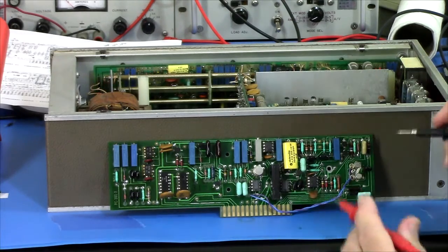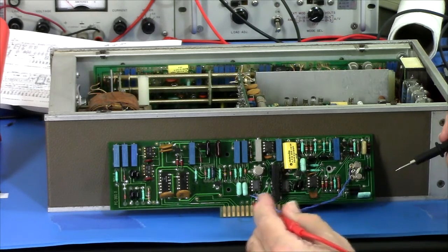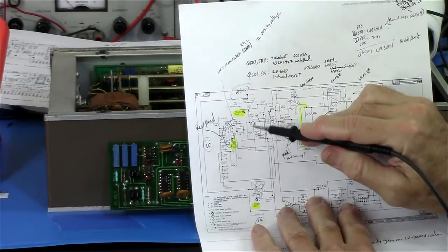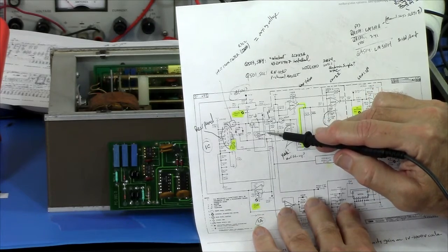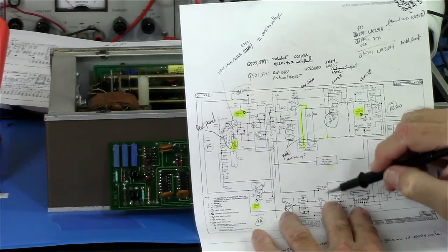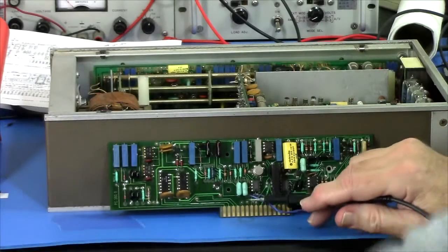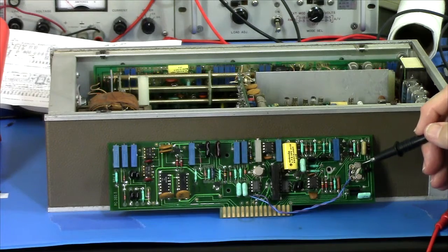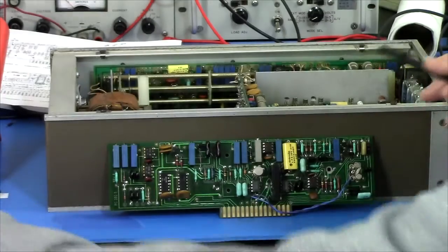Okay, but this is the gate. How do I know that? Well, because it comes over to these test points here, and looking at the schematic, the gate. Let's look at this one. This comes around. Where does it go? Oh man, it goes way over here, and there's test point 20, and the other one is test point 21. Okay, and those are these right here. So that's the gate. The center one is the case. That center connection here.